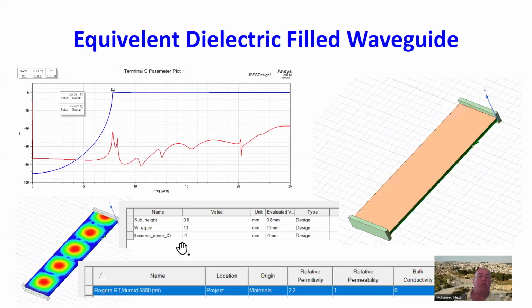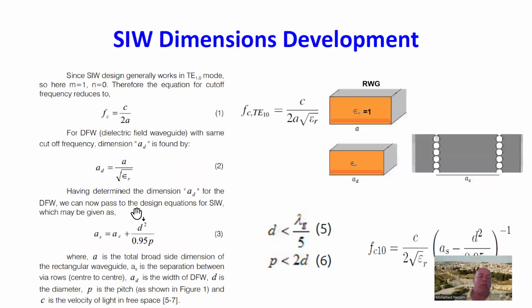That's another thing I forgot to tell you. Now, when you try to choose the diameter of the via, not only does the diameter of the via have to be at least less than 20% of the wavelength at that particular frequency in the substrate, but it also has to be manufacturable. As you know, when you're designing a board, you choose a set of vias and you stick to those. You say a via of 5 mils, a via of 10 mils diameter, and so forth. So really, what you can do is choose a number for a via.